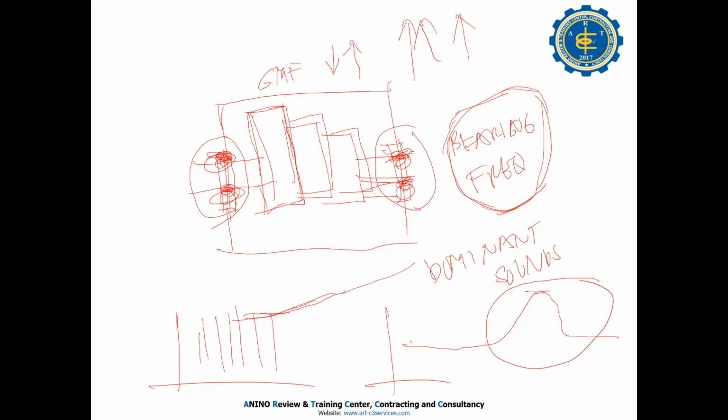So now what would be my action? Should I tell them to change the bearings of the motor or the bearings of the gear? I cannot tell you directly. I want to see first the spectrum, the bearing housing of your gear, and the spectrum of your motor. Can we share the screen here?